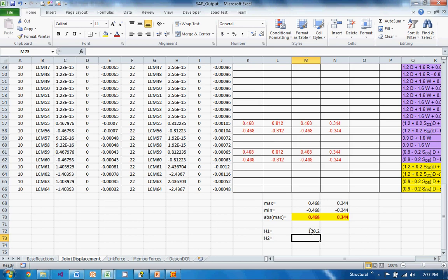I could have potentially picked this one for the drift, because the shear deformation between this long beam is very little. And then when people compare drift, they typically take it to the floor height, roof height or the floor height. So this one is not quite the roof, not quite the floor.